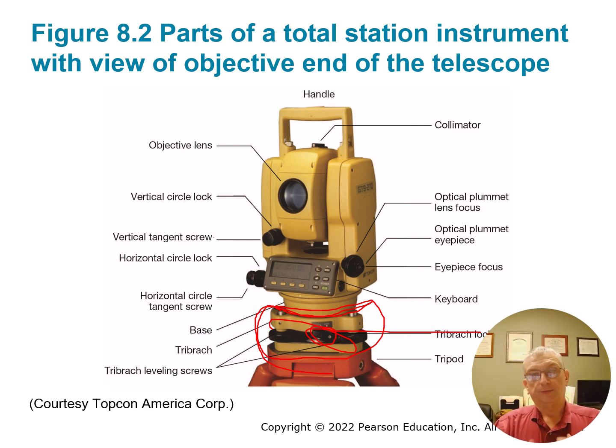Now, sometimes if we're using fixed plate prism targets on tripods, we'll use an optical plumb the whole way. The optical plumb is what we'll use to begin with. We'll set a target in it. The total station will be set up on another tripod in another tri-brac, and then you take the tri-brac lock, unlock it, pull the total station out, put the backside prism target in there pointed towards the forward station, carry the instrument ahead, unlock that tri-brac, take the forward prism target out, set the total station in it, lock it in, and then move ahead with the forward tri-brac and target.